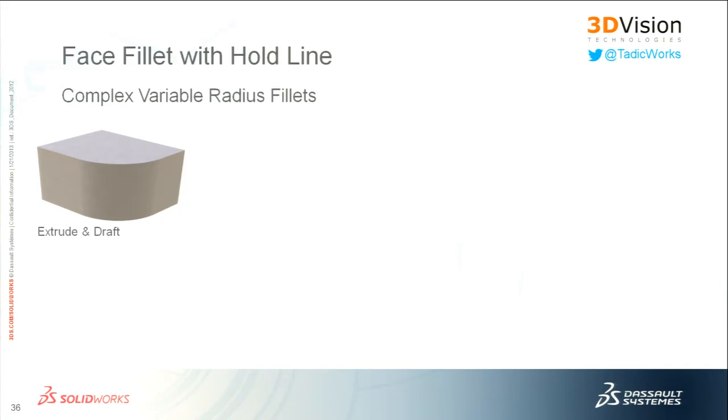What I always like to do is break things down into their most simple form. Since that's symmetrical, I'm only going to create a quarter of it and then mirror it a couple of times to create the rest. I extruded that guy with draft. Then, from the images, I just plopped them into the part file and traced over the curvature that I saw for each one of those ribs. It kind of steps out each rib.